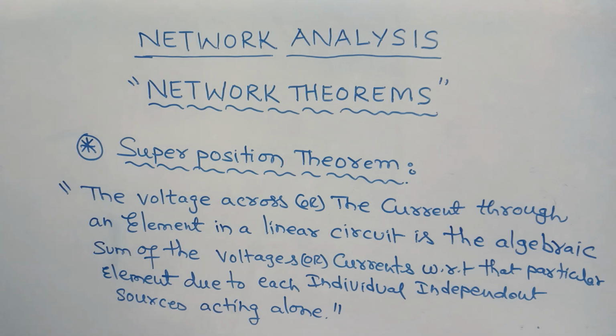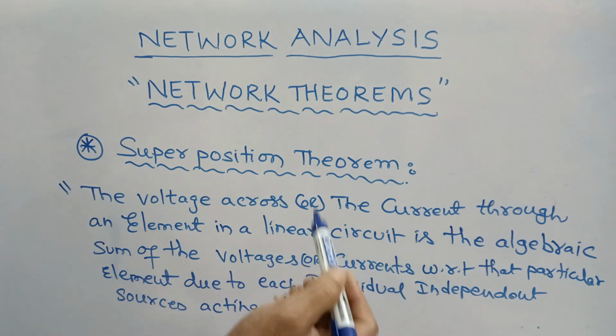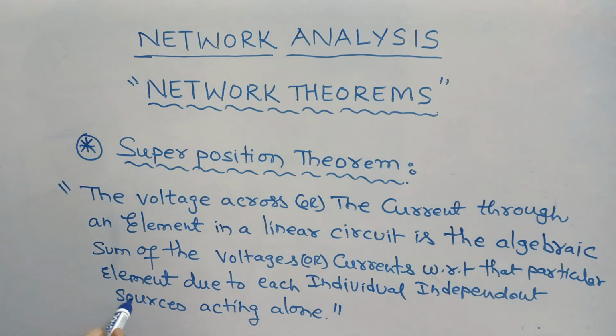In today's presentation, I would like to explain the superposition theorem. The superposition theorem states that the voltage across or the current through an element in a linear circuit is the algebraic sum of the voltages or currents through that particular element due to each individual independent source acting alone, right?